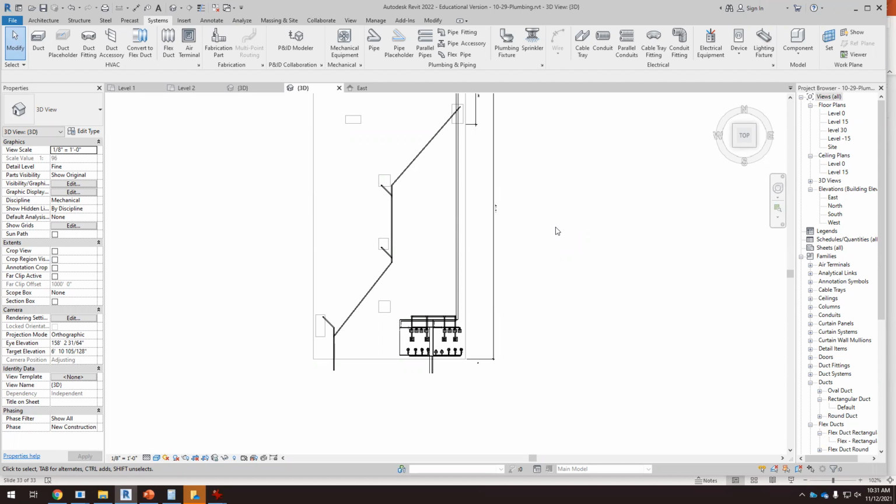Okay. But it's something that doesn't matter because it's underground. So it's not like the air ducts. The air ducts can be either exposed or through the false ceiling. So we have to be careful with that because they are within the building. But this is out of the building, it's underground. So the layout doesn't matter. The only thing that matters is that connections should be 45 degrees. Don't make 90-degree connections because 45-degree connections are better.